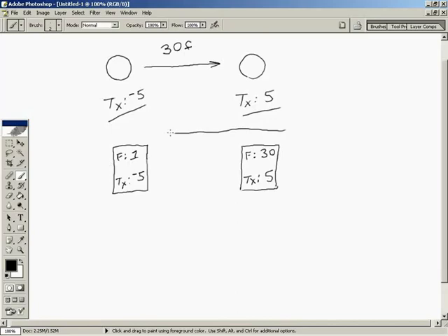But by creating the very first keyframe, guess what we have done? We have generated a new node in Maya, because this information is stored in this node. So here's the node. Remember how they draw them as big rectangles? It is an animation curve node. And this node contains the data that you have recorded. Basically, at what frame, what was the value, and what are the tangents. And tangents is something we're going to talk about a little bit later when we start talking about interpolation curves. So all of that is being stored in the animation curve node.